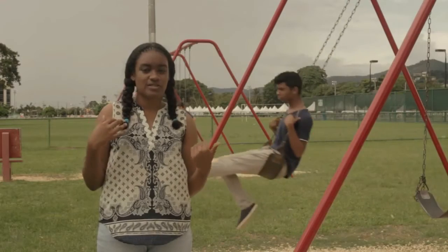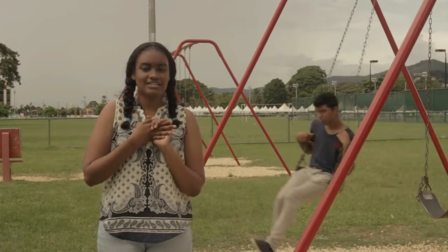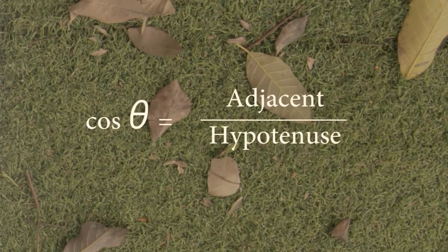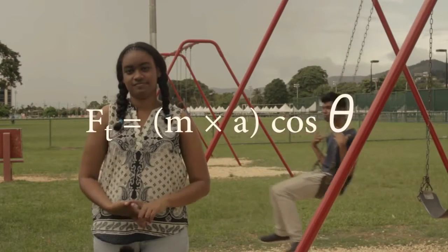The next force we seek is the tensional force. As previously stated, this is the force along the swing chains. Its angle is the same as previously used. The trigonometric identity we use, however, is cos theta is equal to adjacent over hypotenuse. Following the same format, we get Ft is equal to mass by acceleration by cos theta.